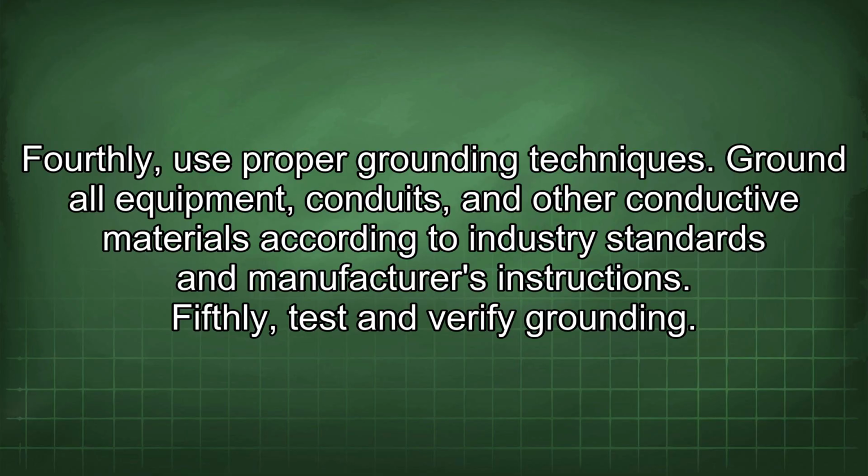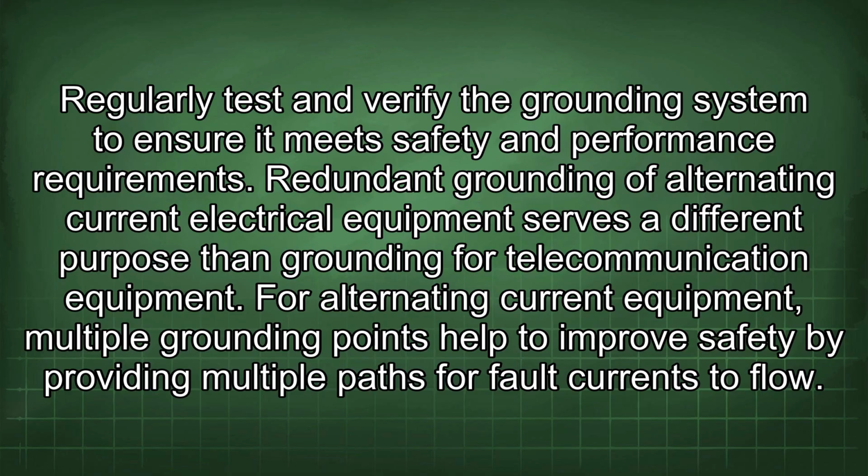Fifthly, test and verify grounding. Regularly test and verify the grounding system to ensure it meets safety and performance requirements. Redundant grounding of alternating current electrical equipment serves a different purpose than grounding for telecommunication equipment.